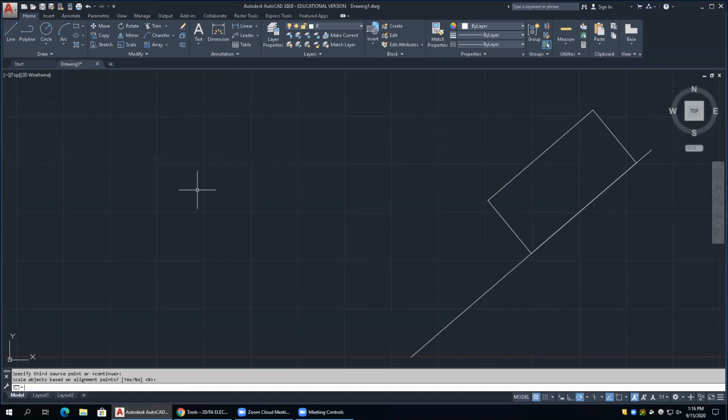And like I said, we're doing what's called a 2D transformation. You can do it three-dimensional as well. Okay. You just need a third source point. You definitely have to utilize O-snaps though. You just don't want to eyeball any of this stuff. Okay, O-snaps are so critical. If you're not picking up on those, that's something that you might want to ask me questions about to help you out with. Okay. All right.